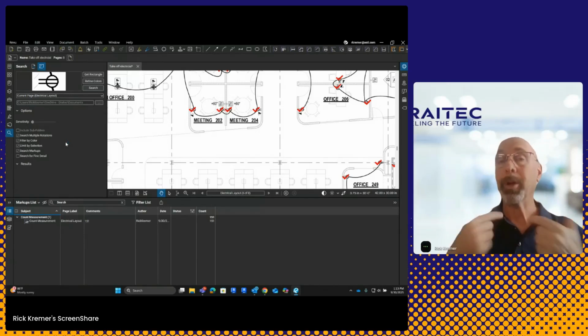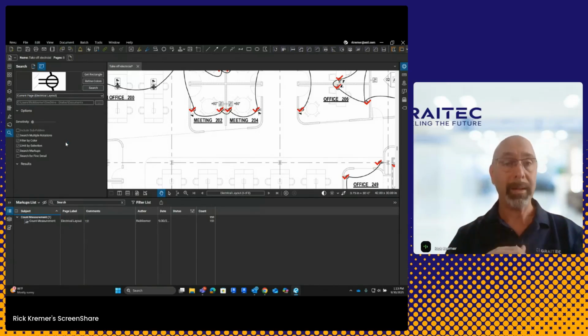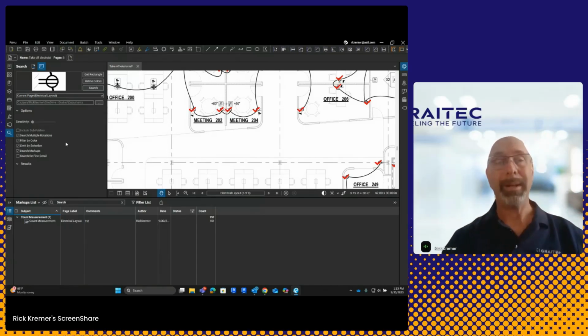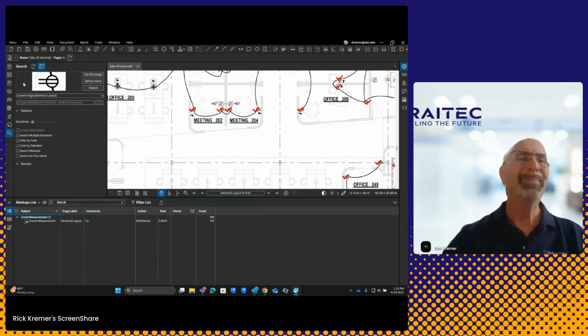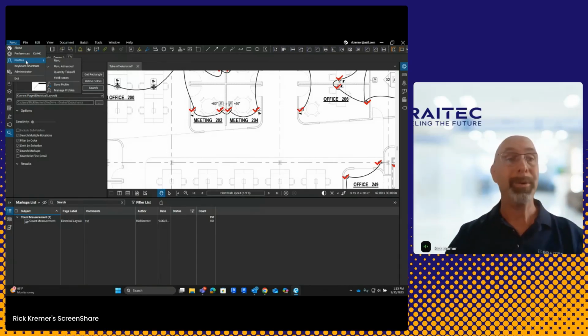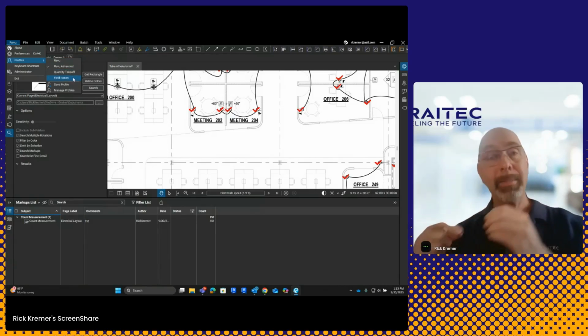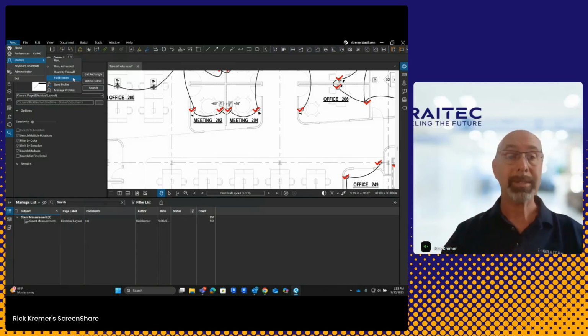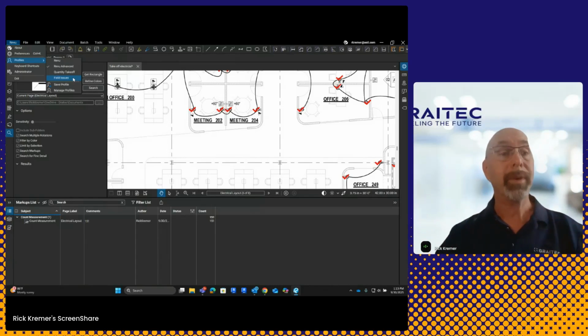What I want to do is I'm going to go through and set up a custom profile. That way I can save my custom tool set to that profile. You're like, what is he talking about? In Bluebeam Review, down underneath the review dropdown, you'll notice there's profiles. Out of the box are the 4 different profiles that come with Bluebeam Review: Review, Review Advanced, Quantity Takeoff, and Field Issues. In order to move forward and customize the type of workflow that I'd like to do, so I have my own icons for electrical outlets, I'm going to go through and create a new profile.